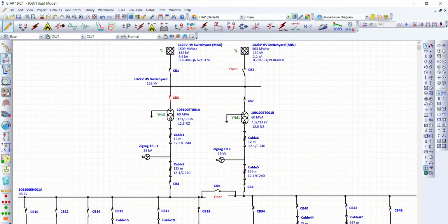In IEC short circuit calculations, an equivalent voltage source at the fault location replaces all voltage sources. A voltage factor c, which we're going to discuss in depth later, is applied to adjust the value of the equivalent voltage source for minimum and maximum current calculations. All machines are represented by their internal impedances.